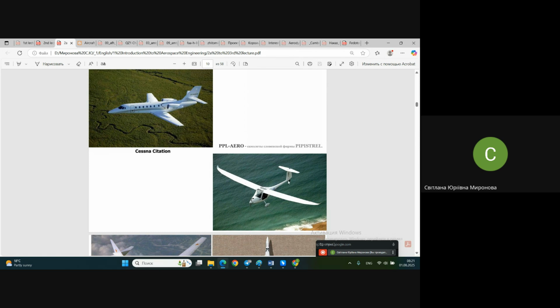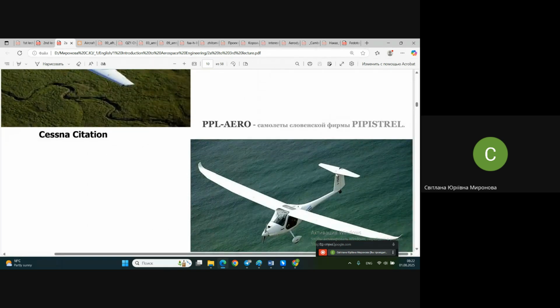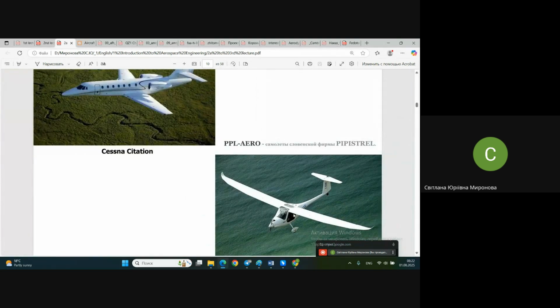The same with the stabilizer. Look, the stabilizer is tapered, practically straight, but tapered, because it has a lateral axis which is not deviated to the back. It's not pulled to the back. It just has a different chord at the root and at the tip, but it's straight. It's a line normal to the fuselage. By the word fuselage itself, look, cockpit and beam. That is how the fuselage is, beam-like.